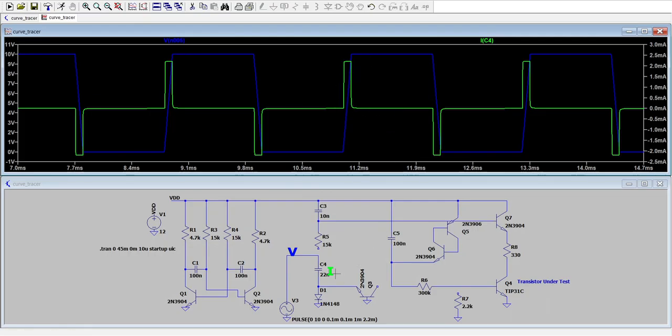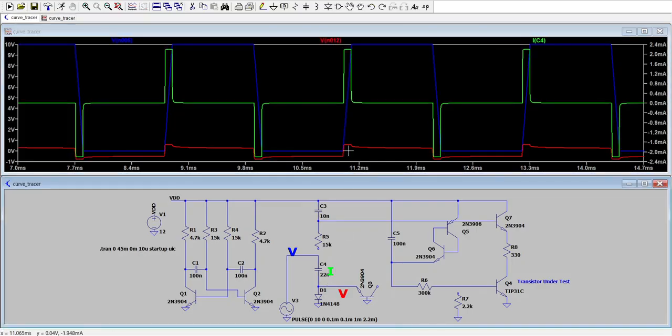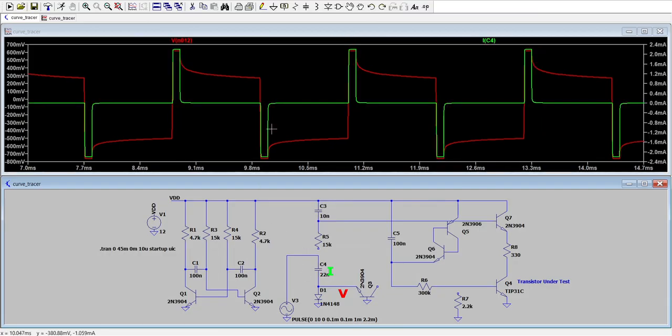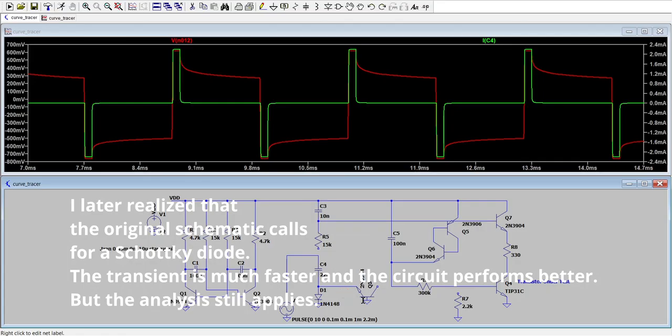In the positive edge, this will give rise to a current flowing through D1, which gives rise to a constant voltage drop. At the end of the rising edge, no more current flows through the capacitor. No current flow means that the voltage drop of the diode should go back to 0 volts. However, you should know that capacitors aren't very happy with sudden voltage variations. Thus, a small current will still flow, giving rise to this transient you see here. The same applies to the negative edge, where instead of D1, the same things happen to the base emitter junction of Q3.